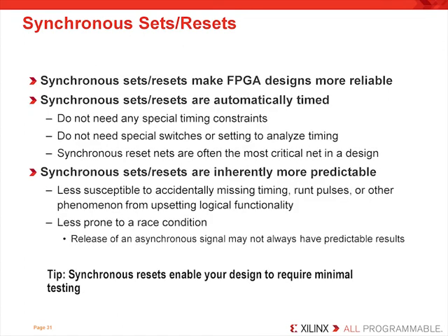A good reason to use synchronous resets is that it is a standard practice of synchronous design techniques. Using synchronous design practices assures that your design won't glitch and greatly improves the reliability of all FPGA designs regardless of which FPGA vendor you choose.